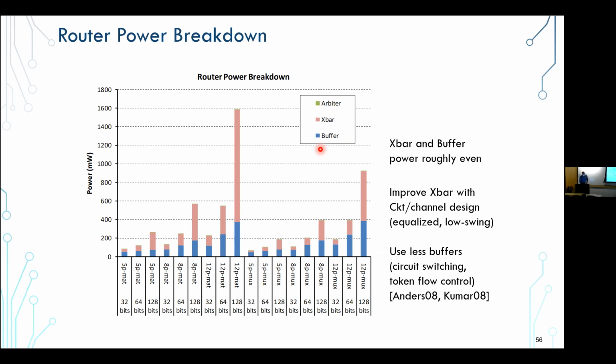In terms of the router power, what dominates is basically the crossbar power and then the SRAM. Even at 90 nanometer, wires are really the ones that take a lot of energy, right? You can scale SRAM, but you really can't scale the wire delays. You need to insert repeaters and do all sorts of things there. So that's why people, I mentioned Valeo back in the day, were talking about 256 radix or 128 radix switches, right?